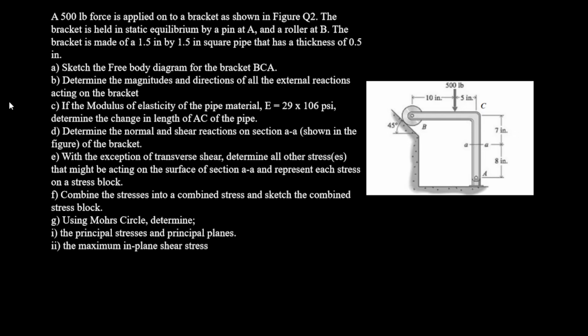Basically the free body diagram is just the structure. So draw the structure, indicate the forces and then their distances from each point. This is the structure of BCA. First of all, we indicate the force at B. It's a roller, so it has one reaction, which we name R. Then resolve the angle in terms of theta, so cos 45 and sin 45. And then A will also have an X and a Y direction, AX and AY. We do that and we get our AX and AY.